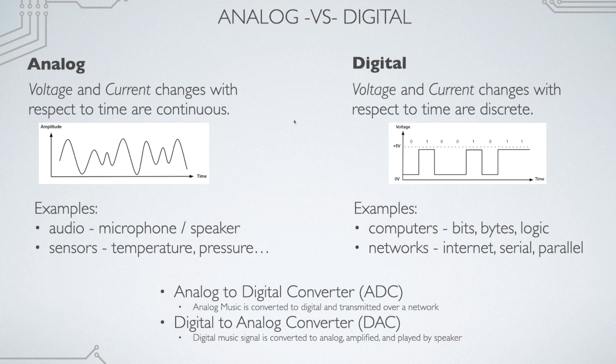So let's take a look at digital signals. Digital signals typically have 2 states. There's an on state and an off state. A 0 or a 1 is typically how we think about these. Physically, if you were to measure what a 1 state is, in this particular diagram, it's something around 5 volts. And the 0 state is something around 0 volts. And so the voltage typically is varying between 2 different states.